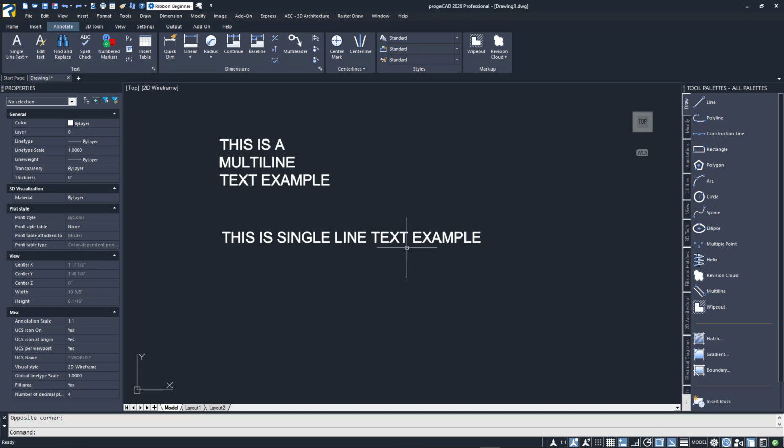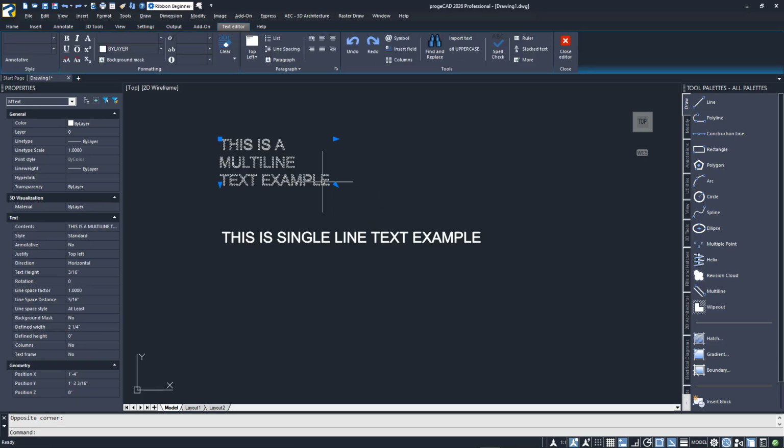Let's double click on the multi-line text now. The interface will return to how it looked when creating the text, which includes the Contextual Editor ribbon tab. All of your editing tools that the font allows will be active here. Most require you to highlight the text in the edit box that you want to apply it to. This is where you can set various style aspects.